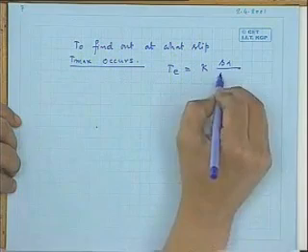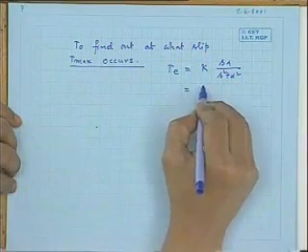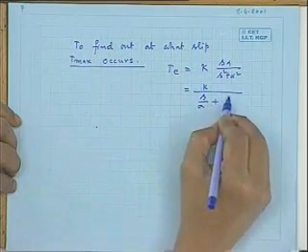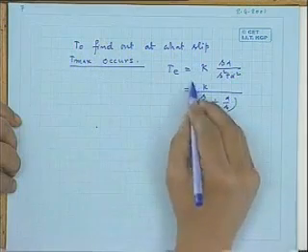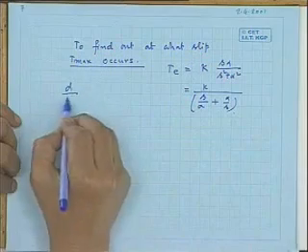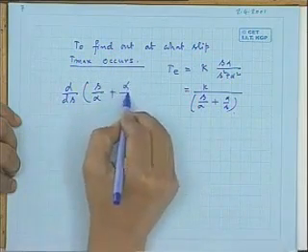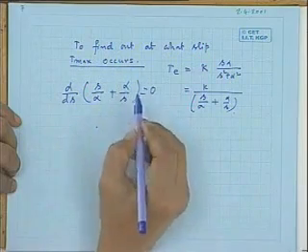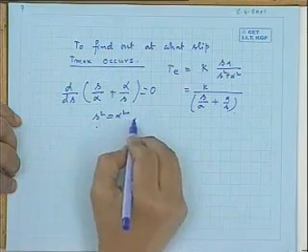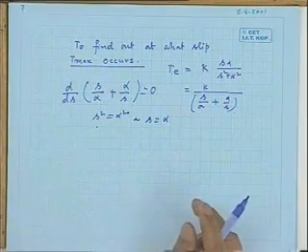As you know, T is K s alpha by s squared plus alpha squared. So you can bring this below, so this will be s by alpha plus alpha by s. So T will be maximum when this will be minimum. So differentiate s by alpha plus alpha by s, set it to 0, and you will obtain that s square equals alpha square or s equals alpha.